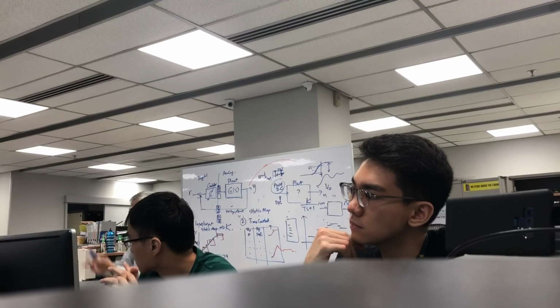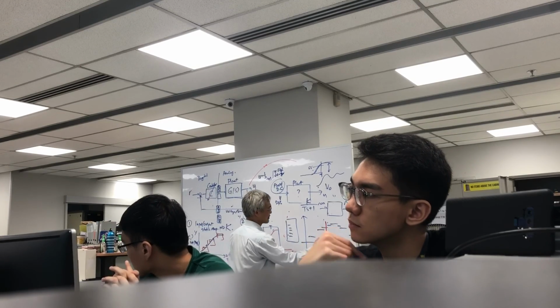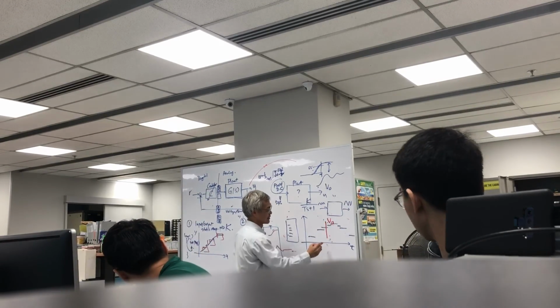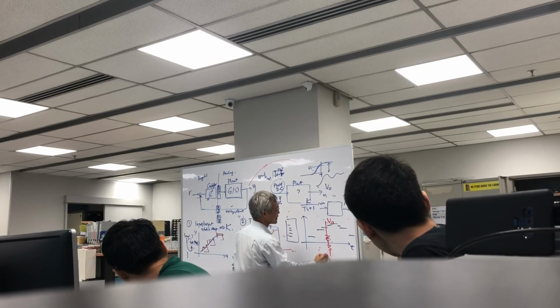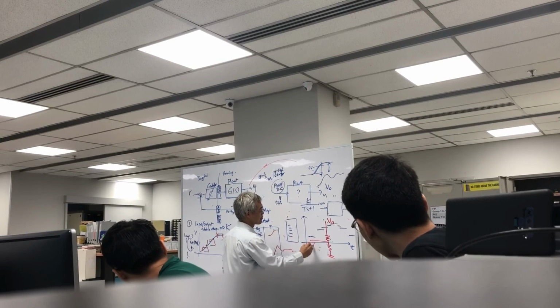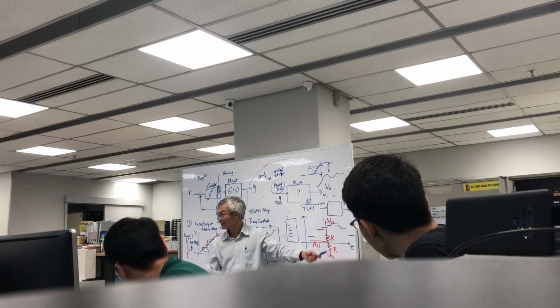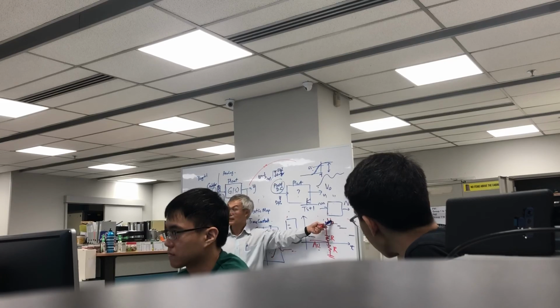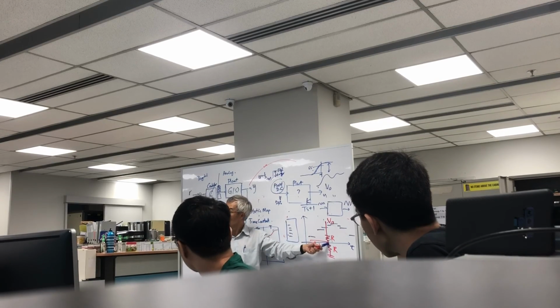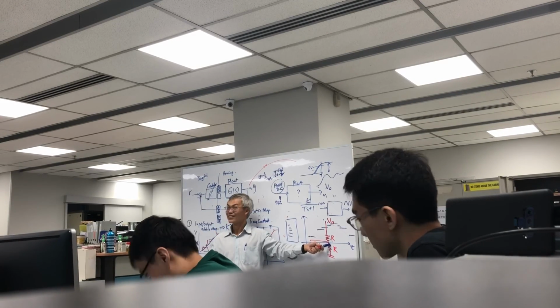Your converter circuit is already there. Lower down like that. This is your V out. Find two identical resistors. Tap from here. Okay? So if this is maximum 10, what is this? 5, huh?